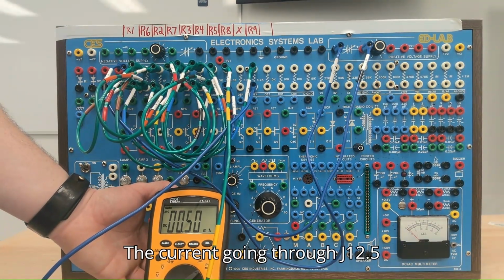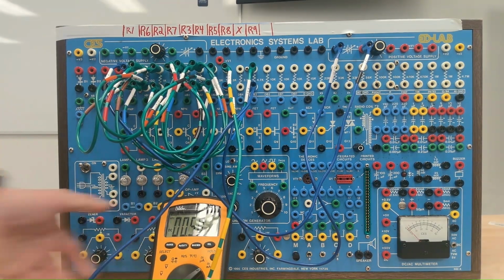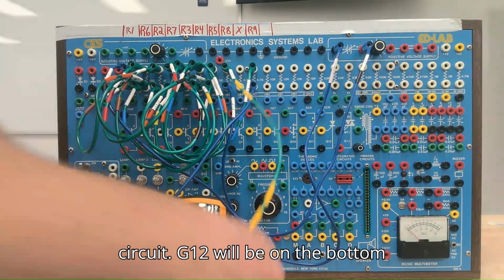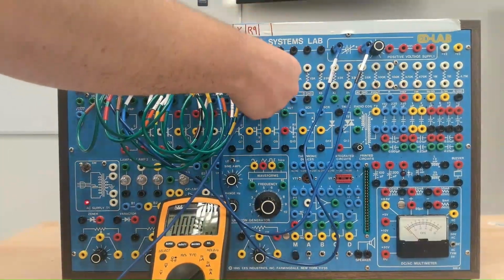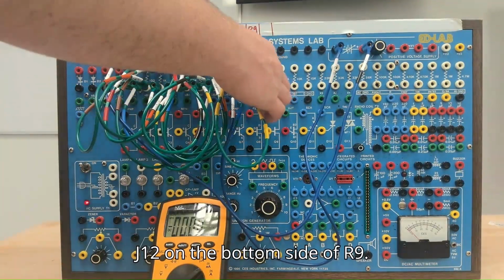The current going through J12, 0.5 milliamps. J12 will be reinstalled back in the circuit. J12 will be on the bottom side of R9. Remove our temporary lead from J12 on the bottom side of R9.